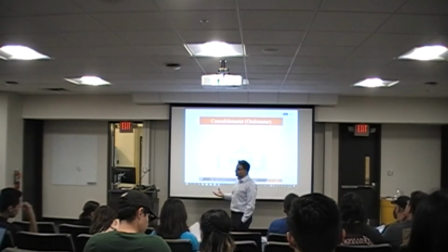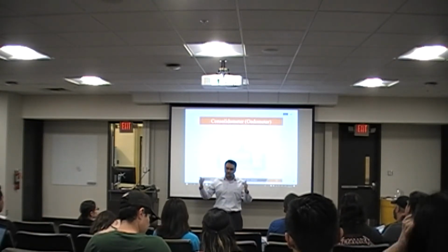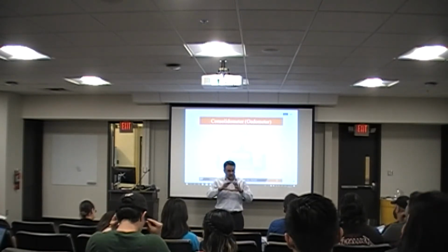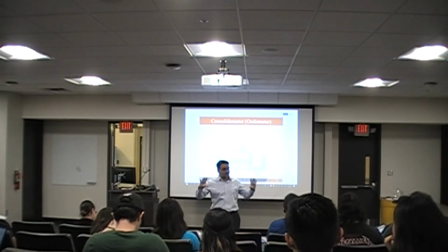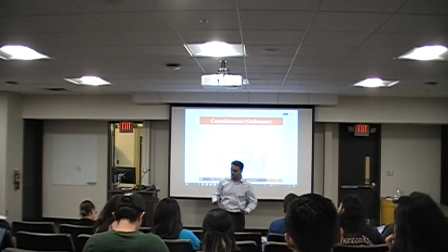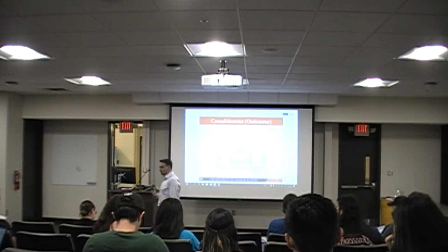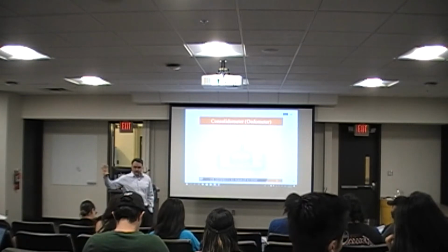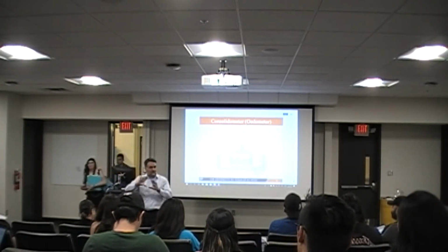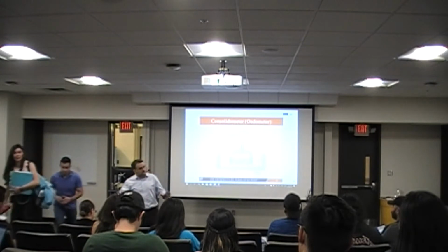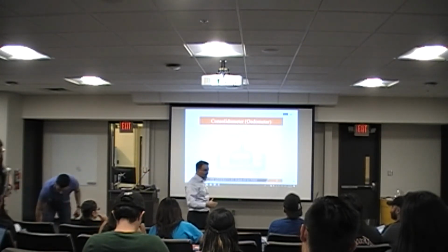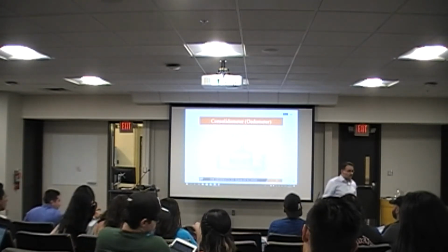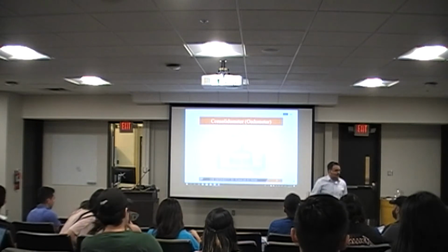And settlement, in very simple terms, is that permanent deformation, plastic deformation that you see at the top of the soil. It's not specifically associated with the top layer. It's basically a cumulative value in all of these different layers that we have. In reality, remember, we talked about soils being multi-layered, non-homogeneous materials, right? So you have different layers, meaning that you can have a sandy layer at the top, you can have a clay layer beneath that, you can have some other type of silty material beneath that. So depending on the layer configurations that we have, you essentially end up with different strength properties, right? And also with different settlement properties.